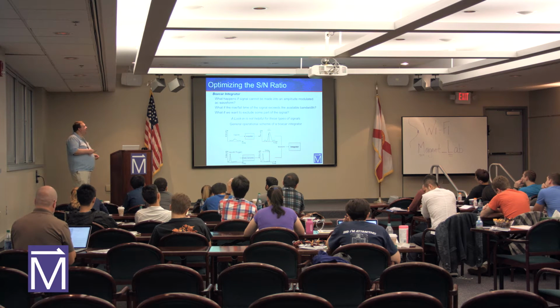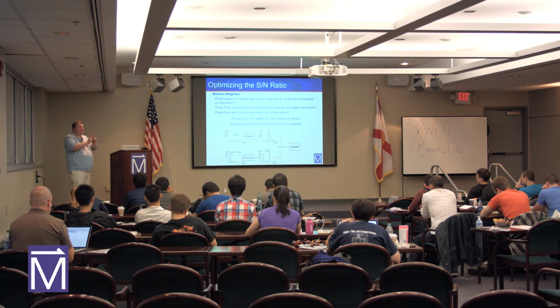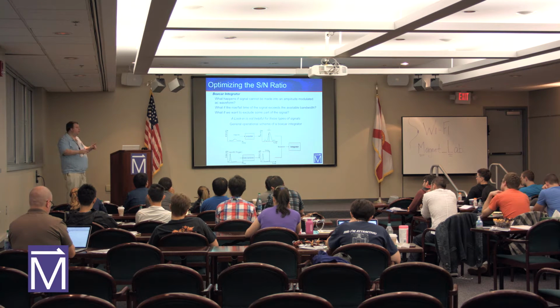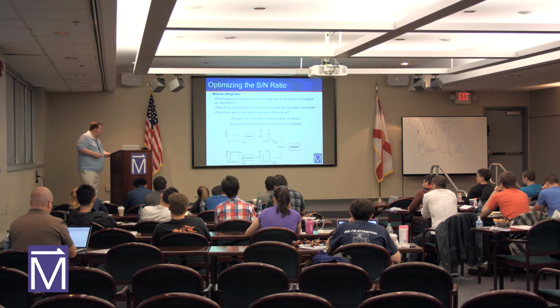One way around that is to use a boxcar integrator. Essentially, it opens a gate over which it integrates, and you can center that on your pulse, and it will reject essentially everything else. So you're eliminating the noise that's coming in while there's no light shining on the detector, and it also focuses on integrating only while you have signal, which is set by the gate that you choose. Therefore, you'll get a much higher response than you might get with a lock-in.